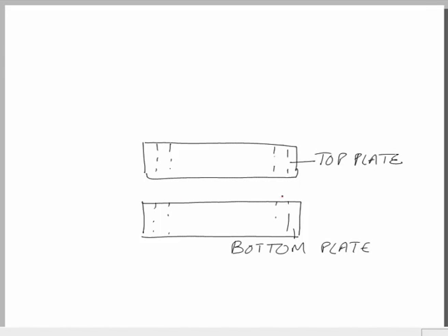In order to have a very good surface finish, we can have a slightly embossed portion on the two plates, and this portion can be ground, or a grinding operation can be done on these two plates, in order to have a very good surface finish.